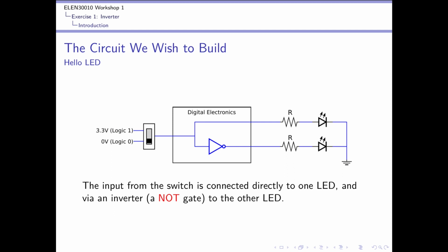Because I mentioned that inside the FPGA it might use a different voltage like 1.1 volts, there's actually some circuitry on the FPGA that changes voltage levels for you. That's a more advanced thing. So anyway, we can have either a logic 0 or a logic 1 flowing in here, which simply means 0 volts or 3.3 volts.